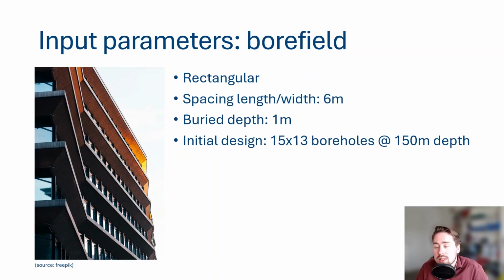Now for the borefields, just to keep it simple, we will stick to rectangular designs. We will stick to a spacing in length and width direction of 6 meters, a buried depth of 1 meter, and our original design, which we will start with, is 15 by 13 boreholes of 150 meters borehole depth.